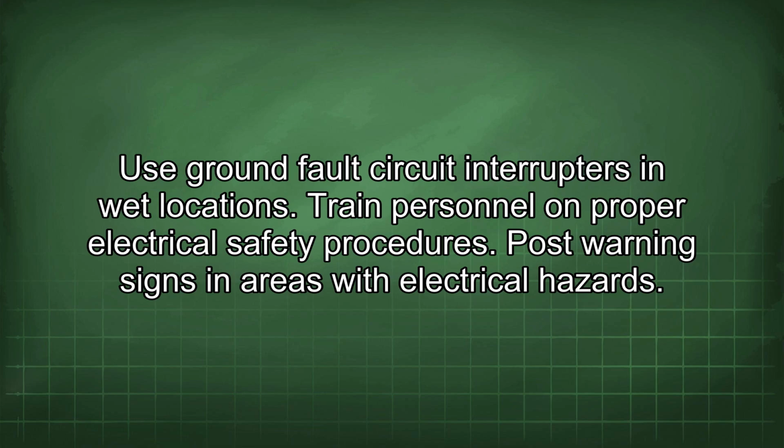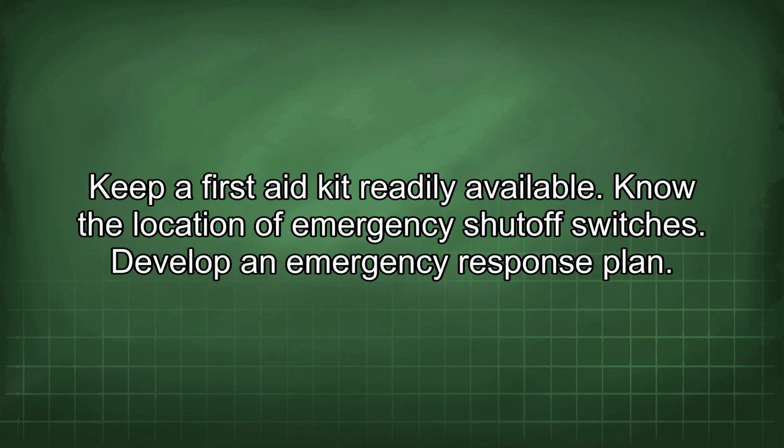Train personnel on proper electrical safety procedures. Post warning signs in areas with electrical hazards. Keep a first aid kit readily available. Know the location of emergency shutoff switches.